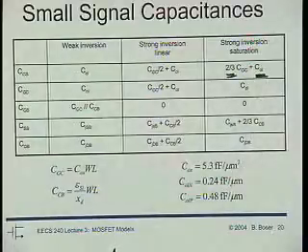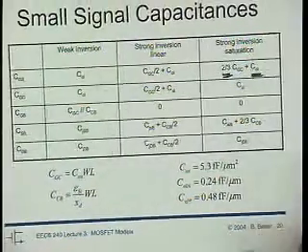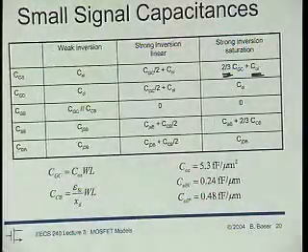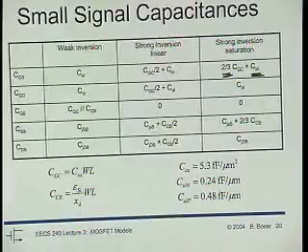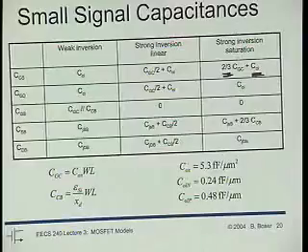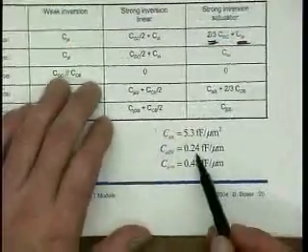One thing that I want to mention is this overlap capacitance. In undergraduate courses, you generally use this LD parameter to calculate the overlap capacitance. It doesn't work very well. What does work fairly well, and generally they actually specify it, is that you build a little SPICE circuit to figure out the overlap capacitance per unit length, or per unit width actually, of the transistor. So I extracted these numbers for our process, running just SPICE, and it's about